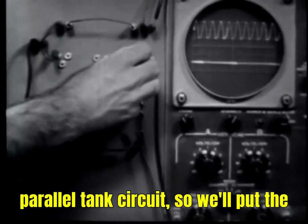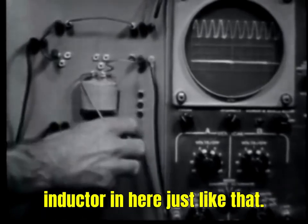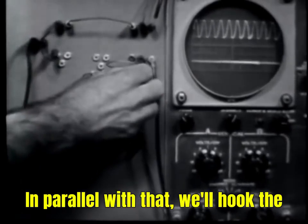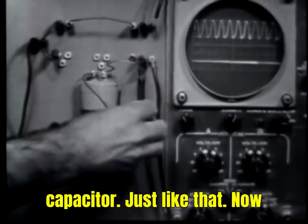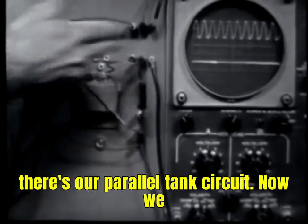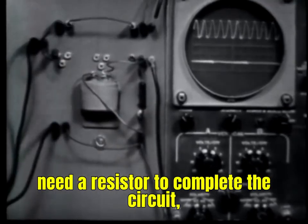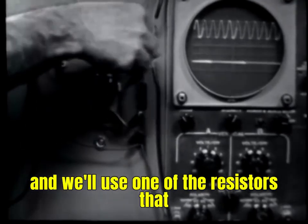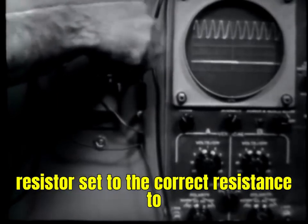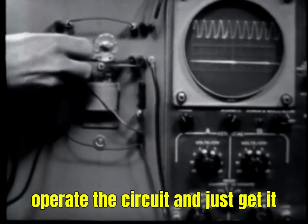So we'll put the inductor in here, just like that. Now, there's the inductor. In parallel with that, we'll hook the capacitor, just like that. Now, there's our parallel tank circuit. Now, we need a resistor to complete the circuit, and we'll use one of the resistors that we used in the first lesson, variable resistor, set to the correct resistance to operate the circuit.